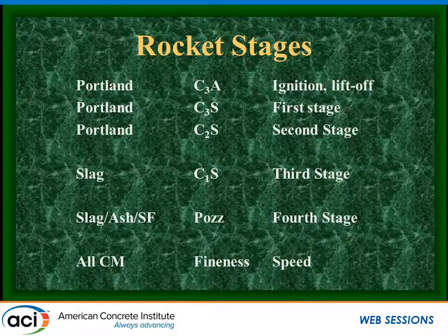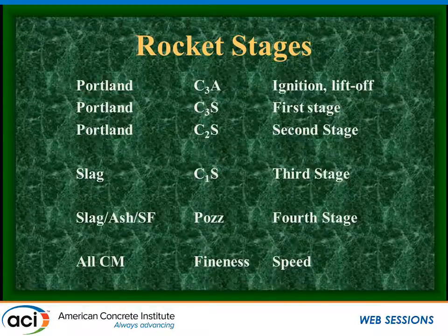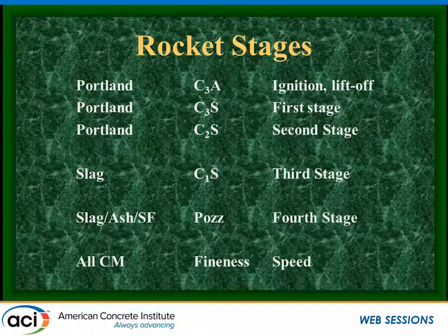Then the first stage, the C3S, is the next most reactive component, and that's going to attribute our strengths from that 1 to 7 and maybe 14 days of hydration. Then the C3S kind of runs its course, then levels out. Then the next stage, the C2S, kicks in, and the C2S is going to pick up where that leaves off, and that's going to get us out to that 28-day mark. And magically, we run 28-day strengths on concrete because Portland cement pretty much runs its course in about 28 days. You will see some minor strength improvements beyond that date, but not very much.